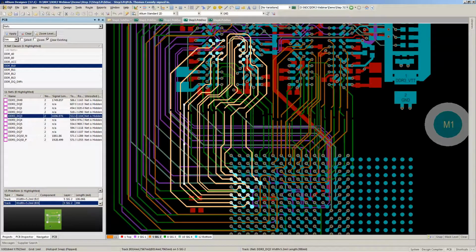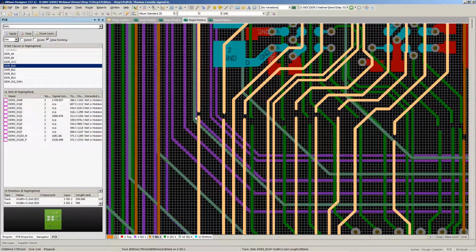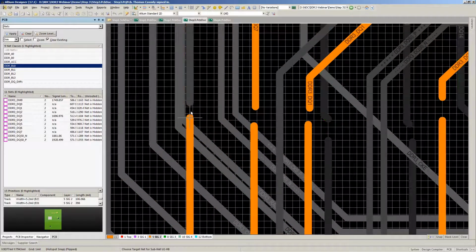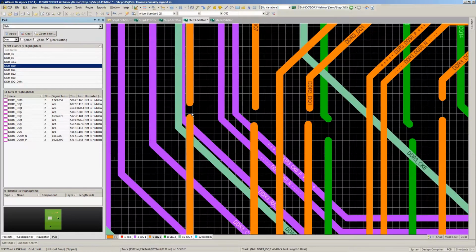I just route the pins as cleanly as I can, but without worrying about which pin is which. You still have to route the DM, the data mask line. So that's one signal you have to make sure you do because you cannot bit swap that. But the other 8 pins are bit swappable. And for Altium, I can show you real quick. They have a nice little effect where I can basically say, okay, I want to make this signal connect to this signal. And what that little motion I just did basically connected those disparate net names on the schematic. So if I was to go back and show you those, the pins would have moved on the schematic, and these signals can now be routed together, whereas these are different, so Altium's not going to let me route them together.